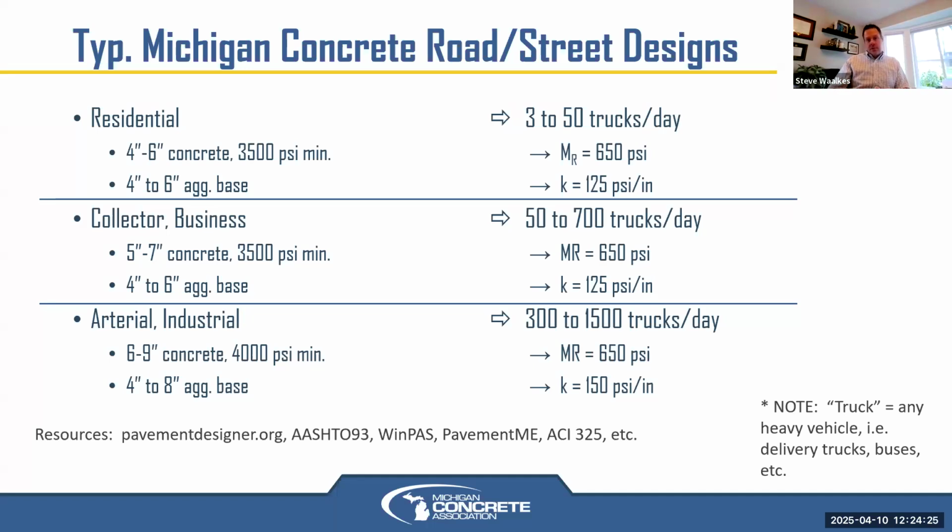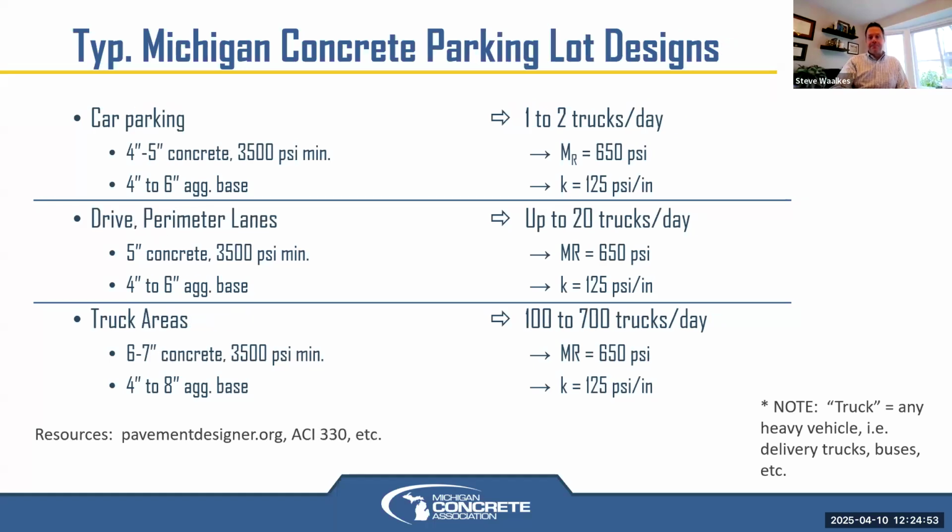So my 4-inch residential driveway can probably only handle one truck a day, at most, driving over it. But if you can go to 5 inches, you can go to 3 or 5 trucks a day, maybe. And if you can go to 6 inches, you can go to 10 or 20 trucks a day. So that's a good rule of thumb. Every inch of concrete adds a significant amount of load carrying capacity.